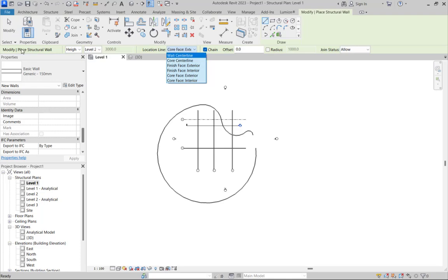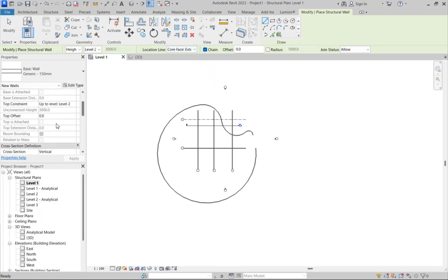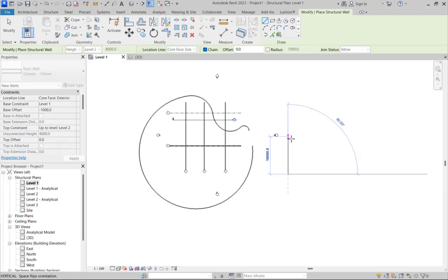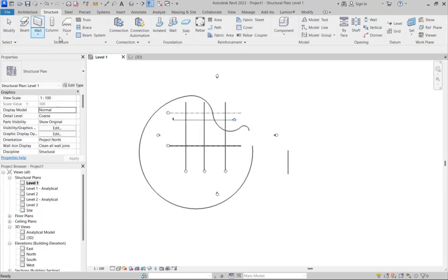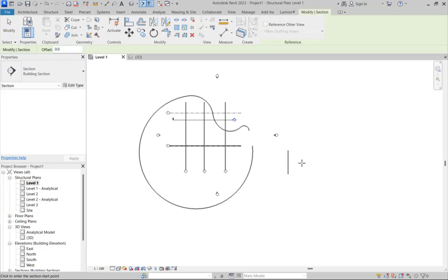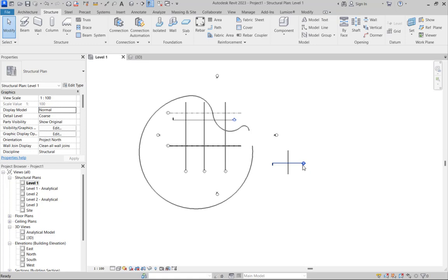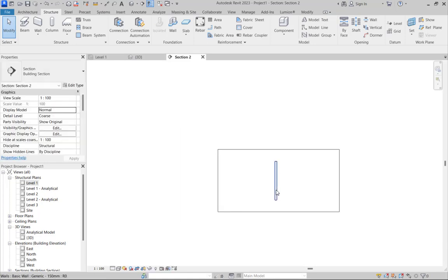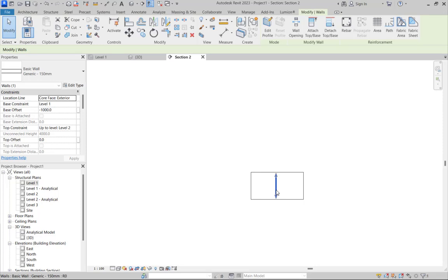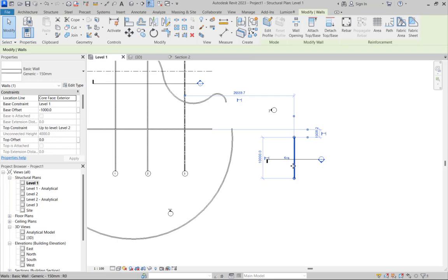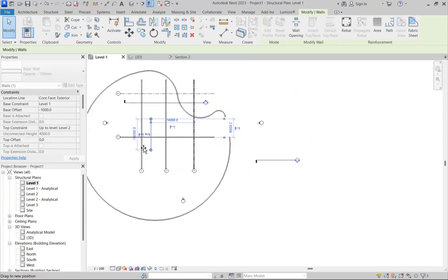Aside that, when you pick your wall, you can also determine the height to which you want to send your wall. From a base level, you can also do minus any height that you want to specify. When you draw your wall like this, and I take a section through, so let me try and bring this wall here.